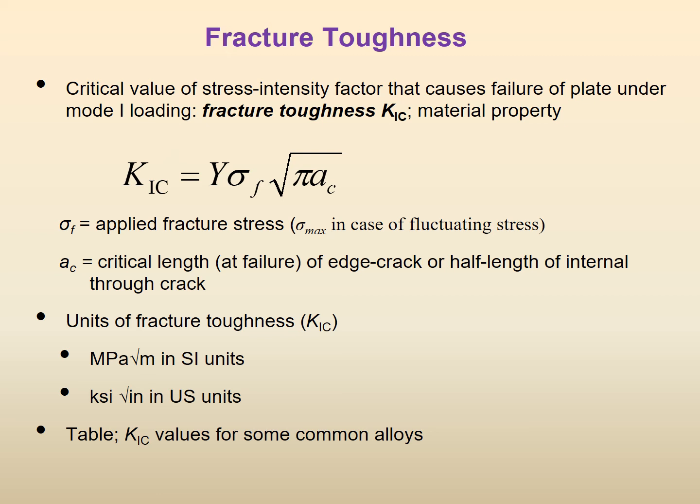You have a crack and you are applying some load. So there is a stress concentration at the crack tip. Will the material fracture? No, it still does not fracture. You increase the applied stress. This crack grows a little bit, so the stress intensity at the crack also grows. The K1 becomes larger. Does it still crack? No, it is still not cracking.